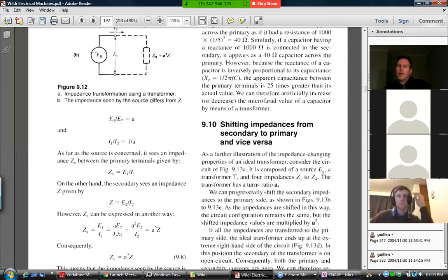This is what the supplier will think the impedance has, in terms of the current that gets drawn through it relative to the amount of voltage that the supplier is putting out. And that supply voltage is seen by this theoretical load impedance referred to the primary. That's the term they use, referred to the primary.